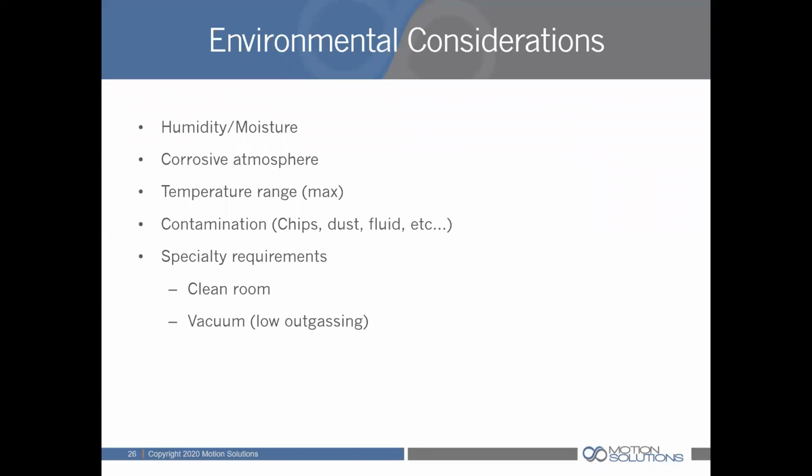Other considerations, of course, humidity and moisture. Just a note on the smaller 2-row bearings that are really suitable for a lot of tabletop instrument type applications: those are generally all stainless steel, so you don't usually have to specify that you want stainless, and that stainless is usually a Japanese version of a 440 stainless, by the way, a 400 series stainless.